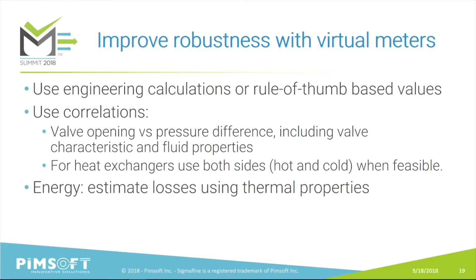All right, and then, of course, you can use engineering calculations. We had customers that, for example, pull the status of a valve, and if the valve is closed and the value is below a certain number, we just put it at 0. Also, for example, for heat exchangers, we might use what we have available, and then we can ask Sigmafine for the rest of the variables that we don't know, like temperature. If we don't measure all four temperatures, the two cold side and two hot side, and we have 3, Sigmafine will help us to estimate the other one. And then, of course, we can use thermal properties to estimate loss, etc.